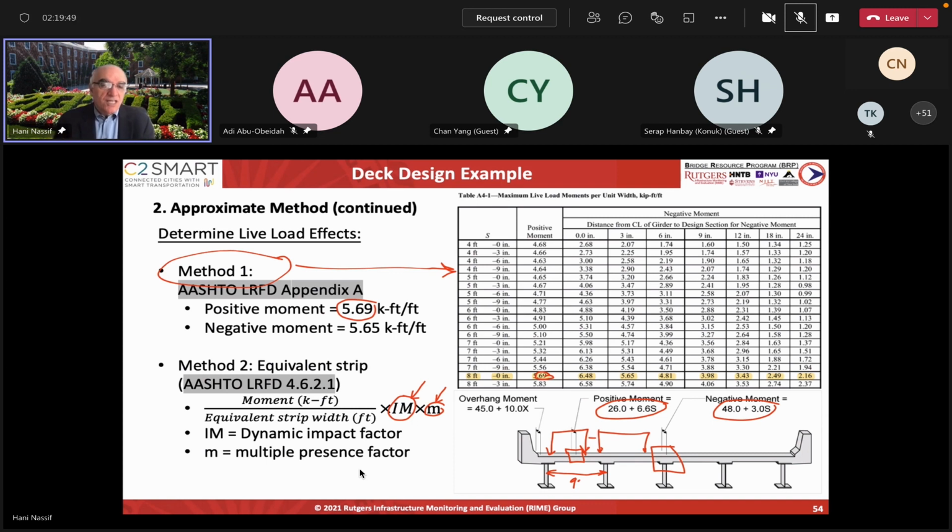Even if they are within the load limit, and so many times they are not, they should be governed by this. And I don't believe that this design governs them properly. The fact that we have arching action, yes, it adds to the capacity. However, the minute you have cracking, shrinkage cracks, or any other types of cracks, the arching action is compromised. You have to have cracks over the support, but if you have a crack in the middle of the concrete, then this arching action is not really reliable, in my opinion.